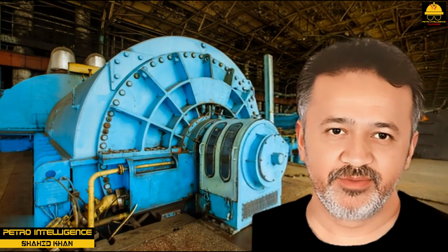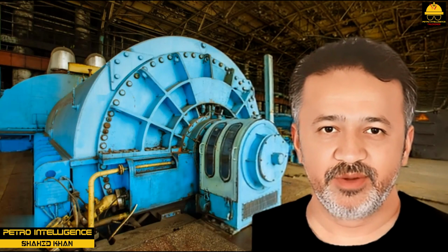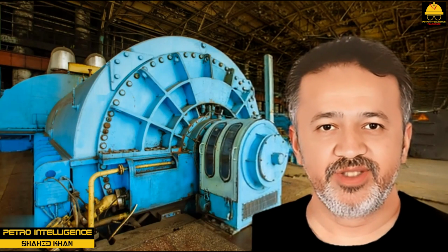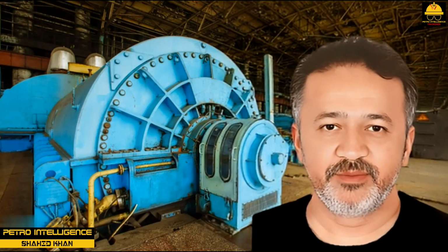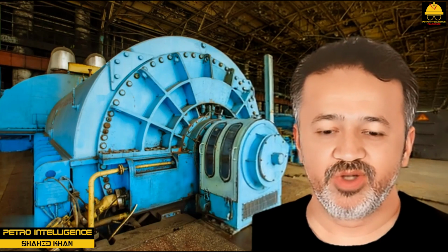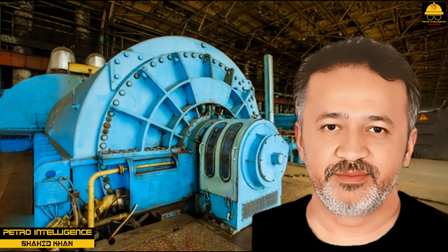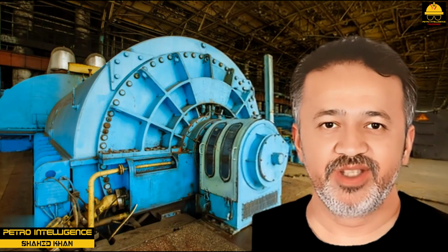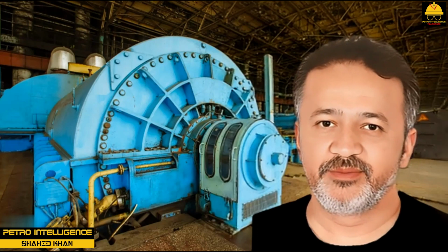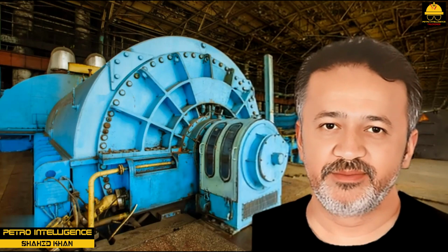An exhaust valve blocks turbine outlet steam. This valve must never be closed when the steam inlet valve is open because the turbine casing could become overpressurized. A butterfly trip valve, which is a heavy-duty valve, is attached to the steam chest. It works independently or in conjunction with the governor mechanism. It is held in place by a powerful trip linkage.